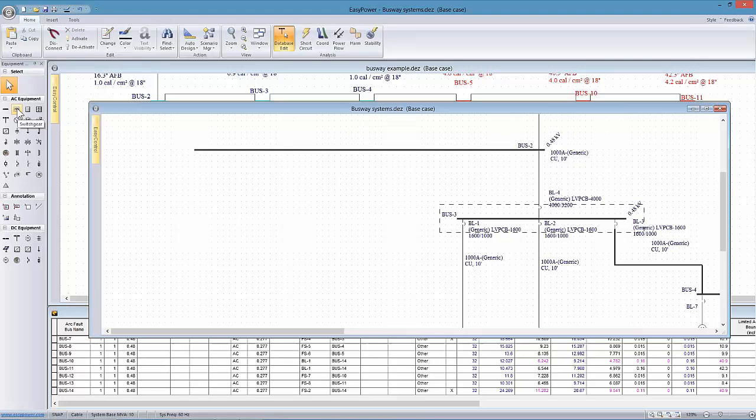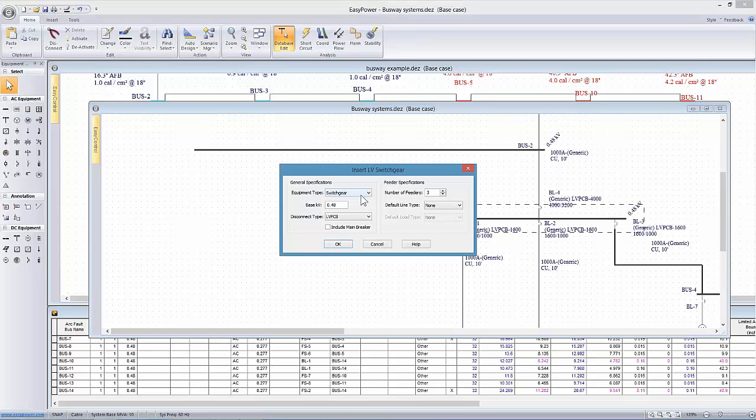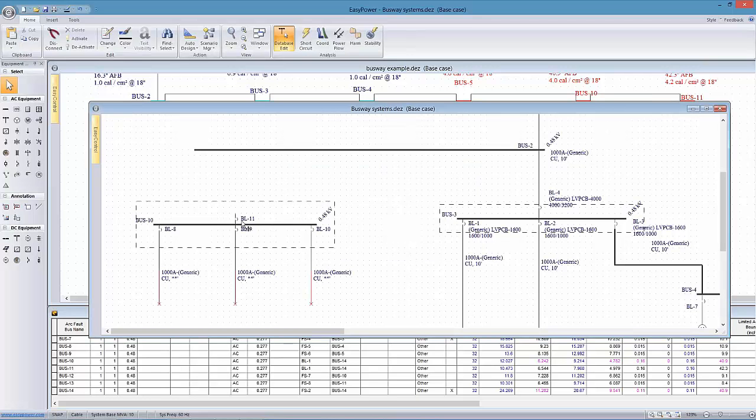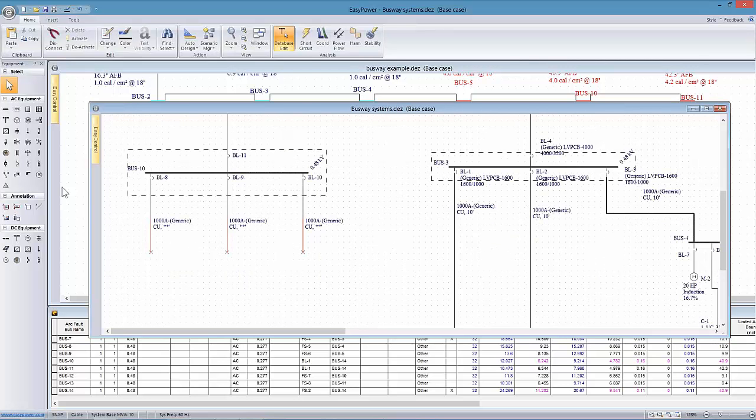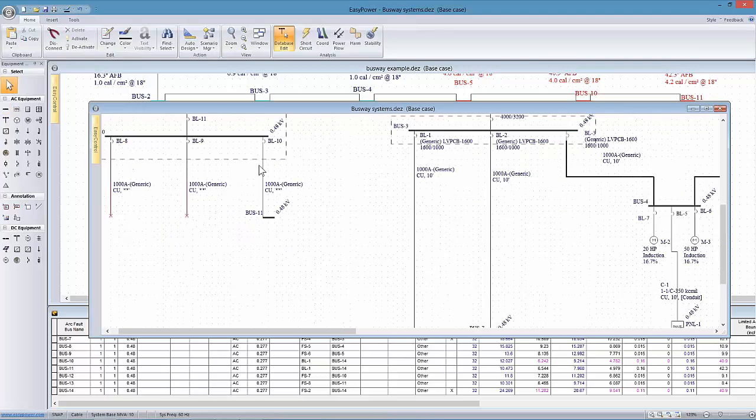I can use my bus switchgear wizard, and instead of using cables, we could use busways, include a main breaker, and now we're set up, in this case, to go with exactly the same type of distribution system. And then when I think in terms of averaging, now this will be the first leg of a multi-busway distribution center. And so I take my busways out just like I did before to the next drop point.